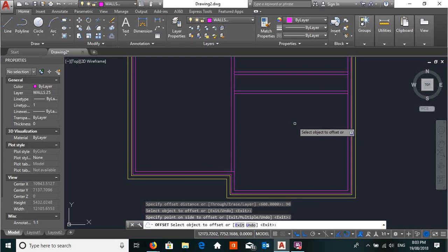So now we need to get this vertical line, and we need to offset that. That was 1000 from the inner stud wall to the other stud wall, or we could look at 1180. Let's do that. So I'll work with this line, because if you look at the measurement, it's easier to work with that.